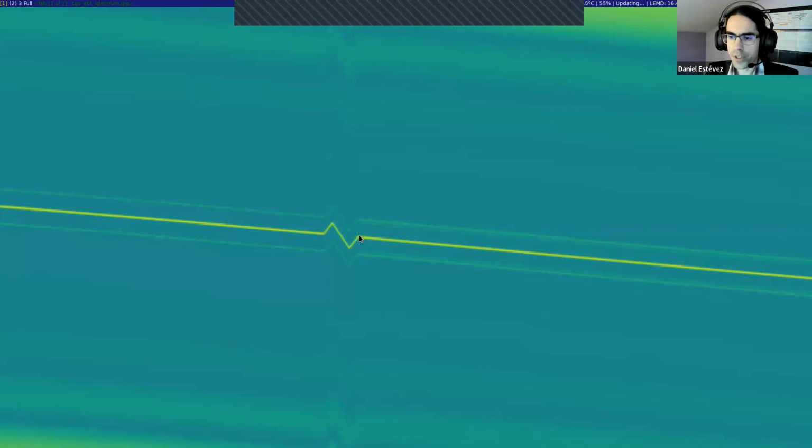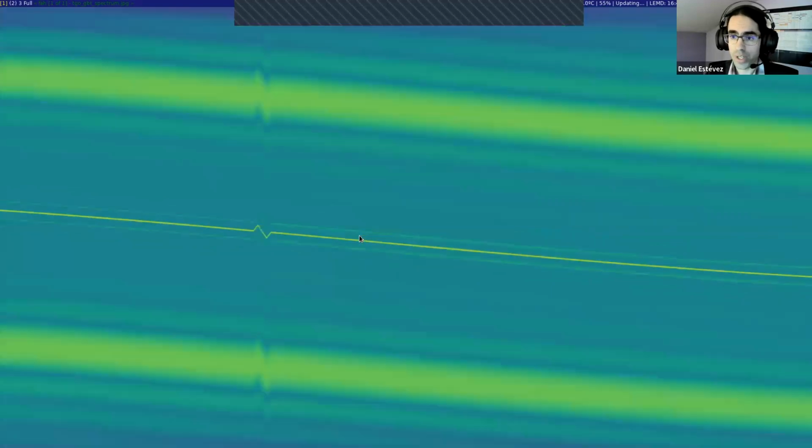So what they first do when they start tracking the spacecraft is transmit an uplink signal, which looks quite similar to this one. It also has a narrowband carrier in the middle. And they will sweep through the spacecraft receiver frequency. And when the spacecraft receiver sees the uplink signal, it will lock to it and follow its frequency.